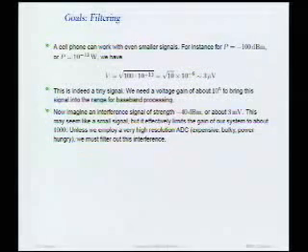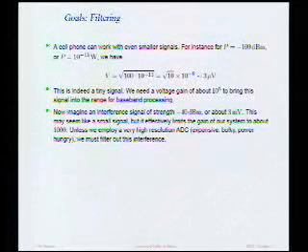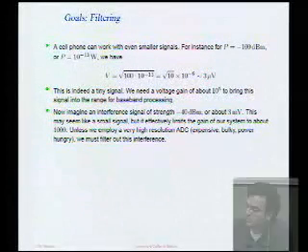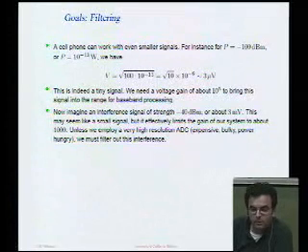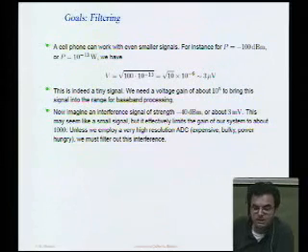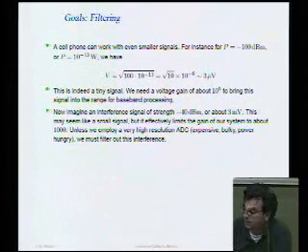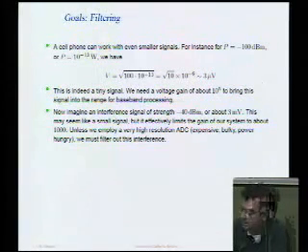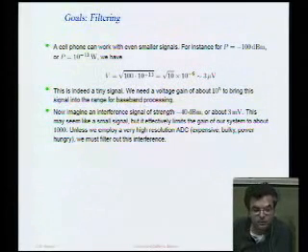But what about for a cellular phone? At the same time as you're receiving that wireless LAN data, you're also receiving, let's say, a cellular telephone call, and the signal there is minus 100 dBm, and the cell phone has to work. Well, how small is that? That's 10 to the minus 13 watts. Using the same formula, if we translate that into a voltage, that's just 3 microvolts. Now that's a really small voltage.